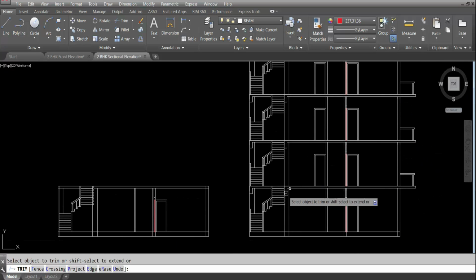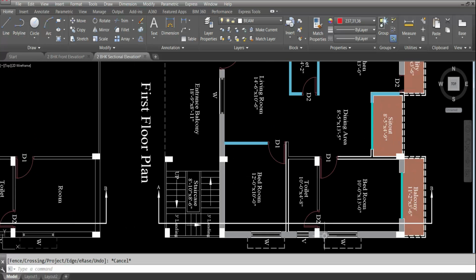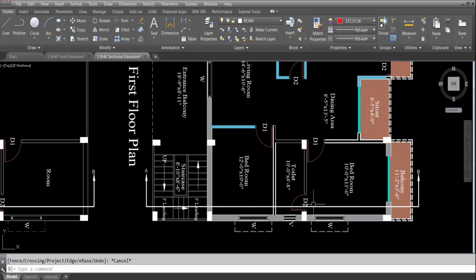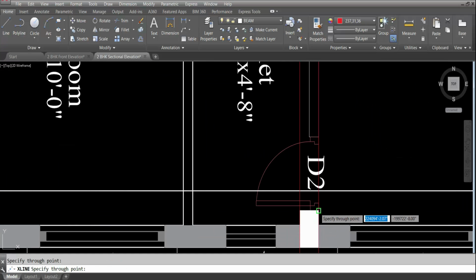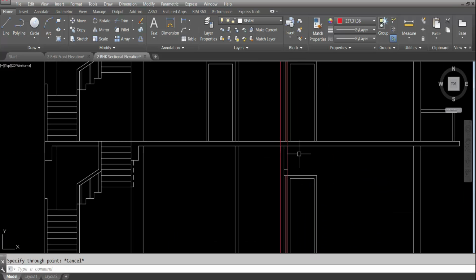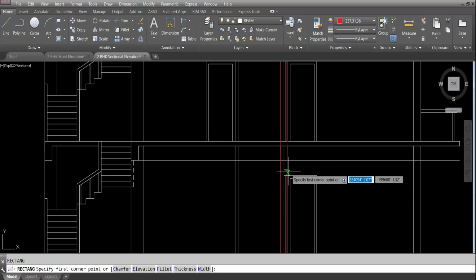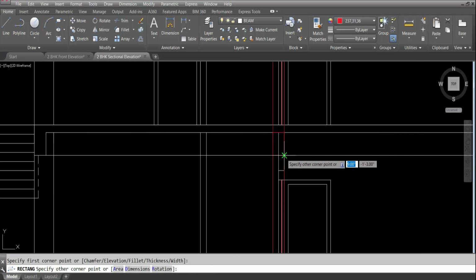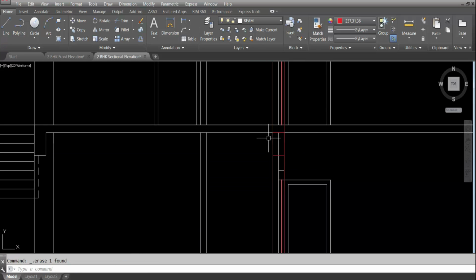Now, here we can see there is no beam. Okay. Here we have to provide roof beam. Now, here. Okay. So column to column, this partition wall, but column is there. That's why beam is there. Beam will be there. So this is 15 inch. Click downward direction. Now rectangle. Specify first point here. Right click. Go to dimension and beam. This is beam is created. Okay. Delete the construction lines.